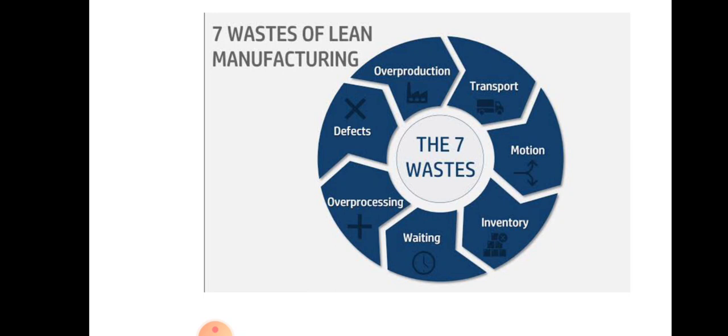excess processing, or you can say overproduction, right? Here in the lean manufacturing system, they utilize several tools to combat overproduction. That means the company should balance the production rate between the departments, right? Measure and process map job results, and reduce setup time, allowing efficient small batch flow. The common causes of overproduction are unreliable processes or unstable production schedules, inaccurate forecast and demand information, unclear customer needs, poor automation, or longer delayed setup time. So lean manufacturing also helps to eliminate this overproduction.